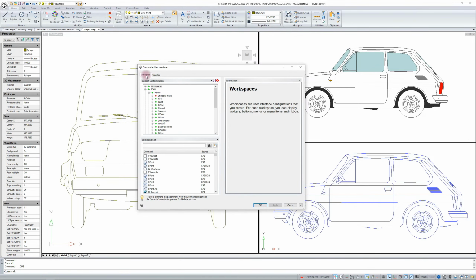On the other hand, if we want to customize this interface on our own, well, we will first use the first tab, and what is very important every time before we leave this window, before we click on OK, this Apply button will be made available. If we don't do this, then unfortunately what we changed won't show up.